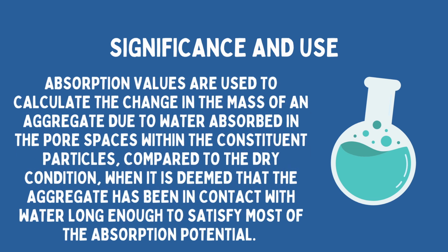Absorption values are used to calculate the change in the mass of an aggregate due to water absorbed in the pore spaces within the constituent particles, compared to the dry condition, when it is deemed that the aggregate has been in contact with water long enough to satisfy most of the absorption potential.